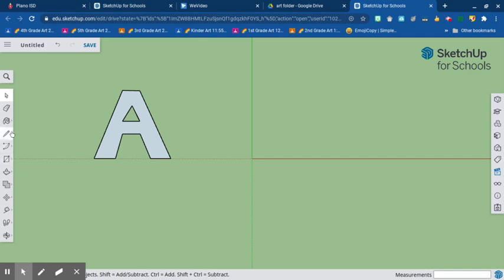Now if you're doing something like the squiggle tool, you can actually come over and hold down your mouse and draw, but you can see how it's pretty difficult to do. So I'm going to undo that one. And I'm actually going to try to use a few different shapes to make my letter. So I'm going to start with a curved line. I'm doing a D right now. And a rectangle. So it'll be a little blockish. I'm going to make my letter D.